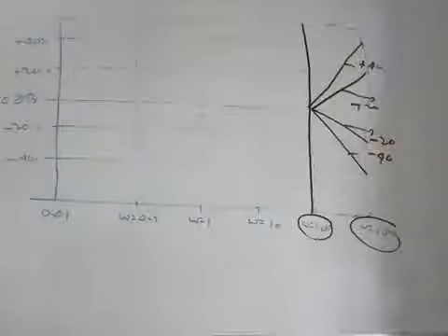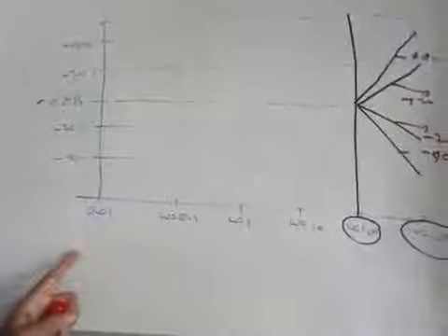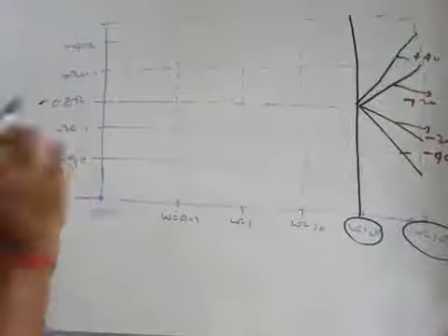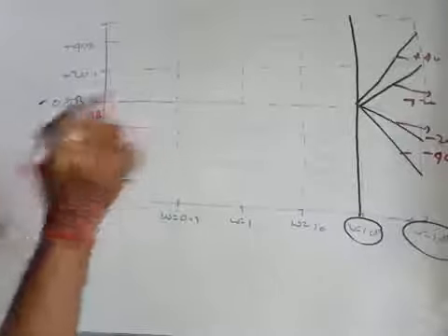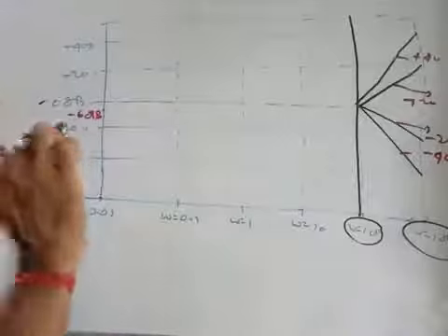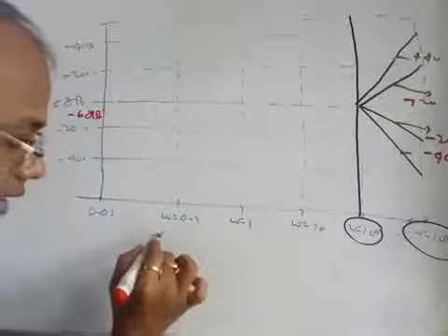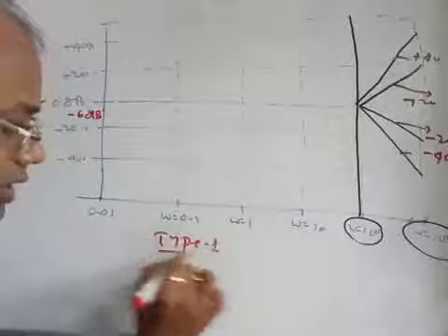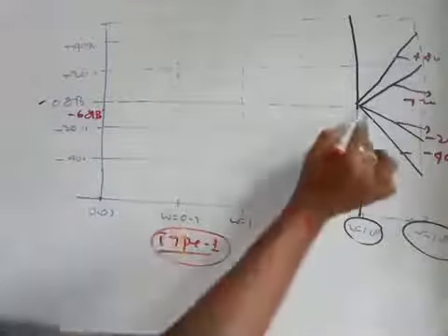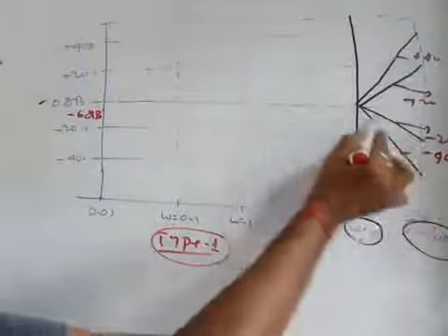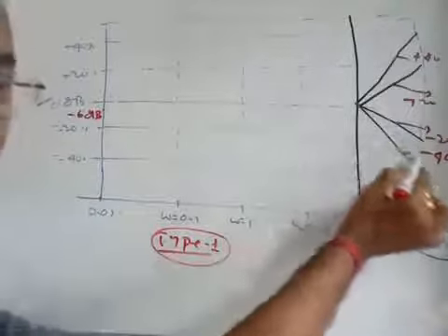Next, what you have to do is check the table, right? Here we will see first of all the initial magnitude, that means at omega equal to 0.01. Now coming to this point, omega equal to 0.01, what is the magnitude? Minus 6 dB. So from this the graph will start, and the initial slope is minus 20 dB per decade, as this is a type 1 system. So just take 2 scales to draw the parallel line of this minus 20 dB per decade.